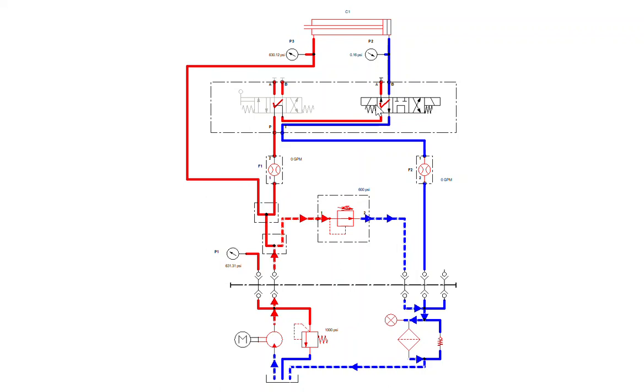When the cylinder retracts, look what's going on in the retract position. Well, let me fully extend it first, and let's watch the retraction. Pay attention to the retraction. Pump flow comes in to the retract port, and flow goes out the extend port and back to tank. So even though there's a very strange connection here, the cylinder still retracts the way it did before. Essentially, to retract the cylinder, pump flow goes in here, and this flow coming out goes to tank.